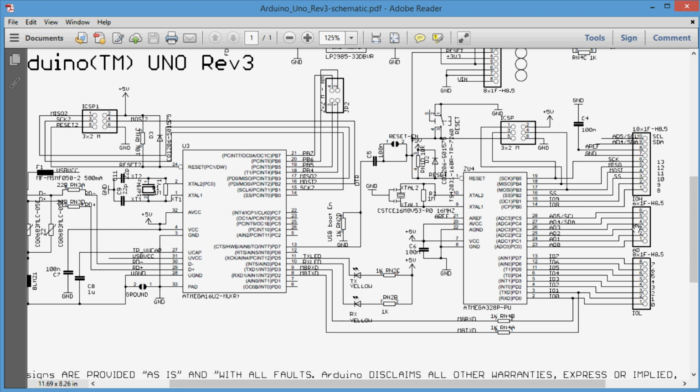Now I forget which other ports I used. I think it was port C pins that I used. I'm not sure. Well, maybe it was port B. Anyways, I used 4 other pins somewhere else on the microcontroller to drive the digit drivers. But these are the segment drivers, and that way I could write out 1 byte to that port, or port D, sorry, and change all of the segment drivers in one instruction.